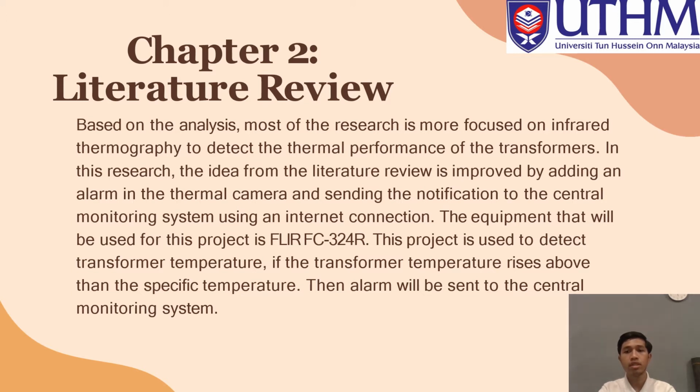The equipment that will be used for this project is the FLIR FC324R. This equipment is used to detect the transformer's temperature. If the transformer's temperature rises above the specific temperature, then the alarm will be sent to the central monitoring system.